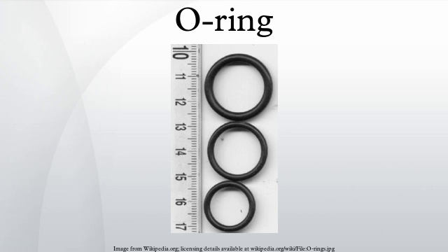There are variations in cross-section design other than circular. These include the O-ring with an X-shaped profile, commonly called the X-ring, Q-ring, or by the trademarked name quad ring. When squeezed upon installation, they seal with 4 contact surfaces (2 small contact surfaces on the top and bottom). This contrasts with the standard O-ring's comparatively larger single contact surfaces top and bottom. X-rings are most commonly used in reciprocating applications, where they provide reduced running and breakout friction and reduced risk of spiraling when compared to O-rings.